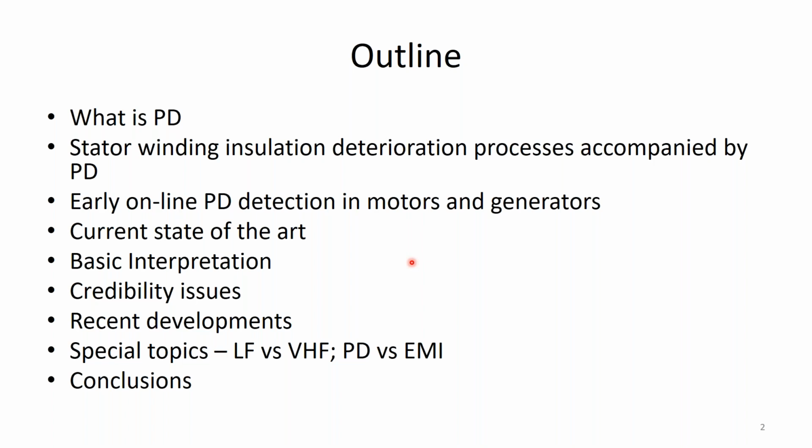to the power system, and that means there's a lot of noise possible. So I'm going to talk about the current state of the art for separating that stator PD from other types of electrical pulse signals. An update on interpretation, what information you can get, what you cannot get, where we still have some uncertainties. And then I'm going to deal with certain credibility issues, limitations, if you want, of online PD testing. There's a lot of commercial voices out there, a lot of vendors out there claiming it'll solve all the world's problems. And after 40 years or so in this kind of technical field, that's just not true.